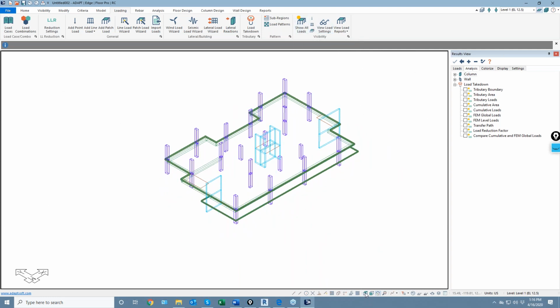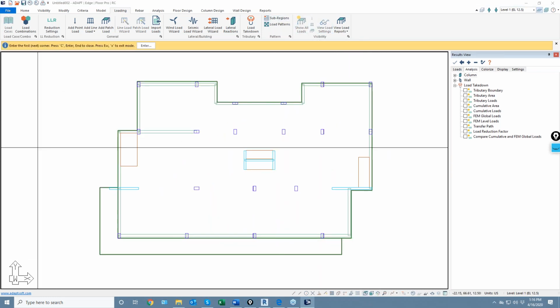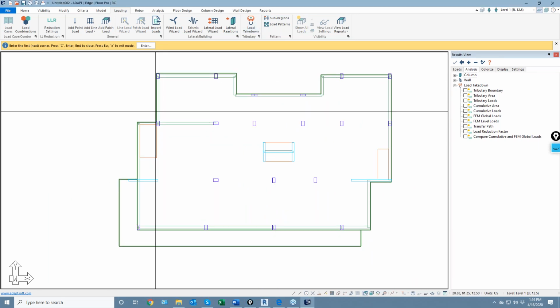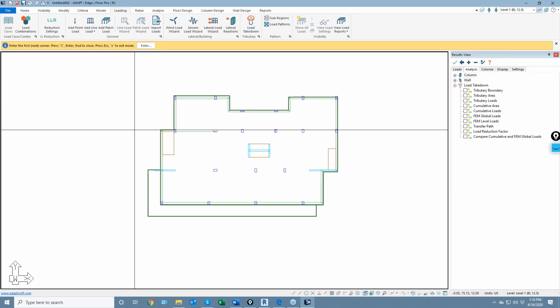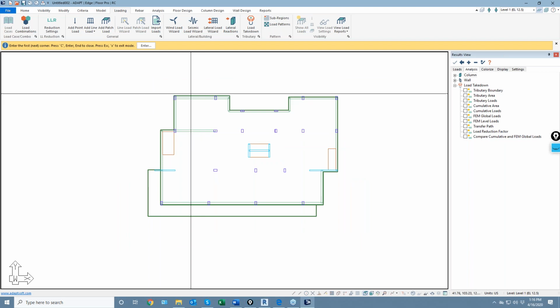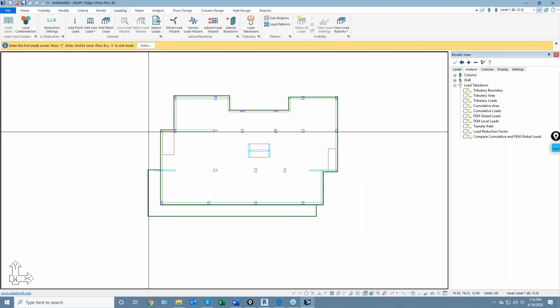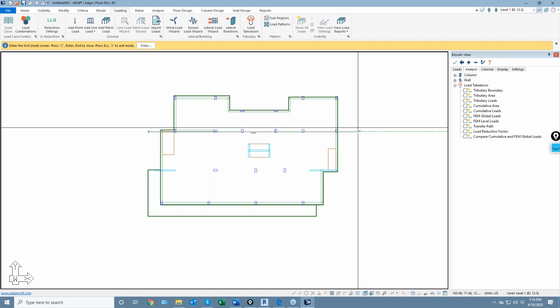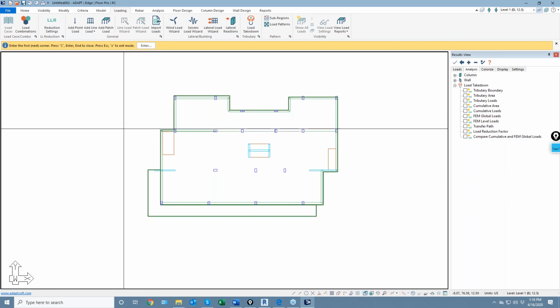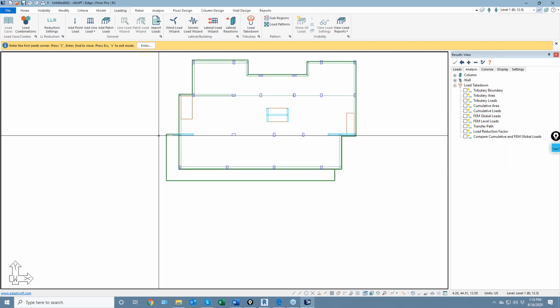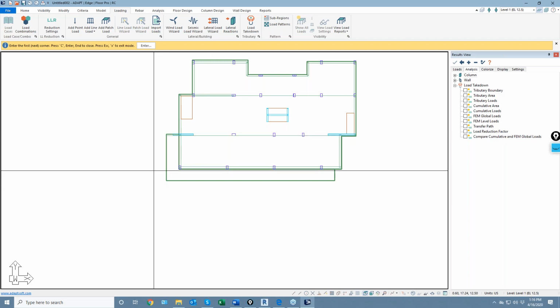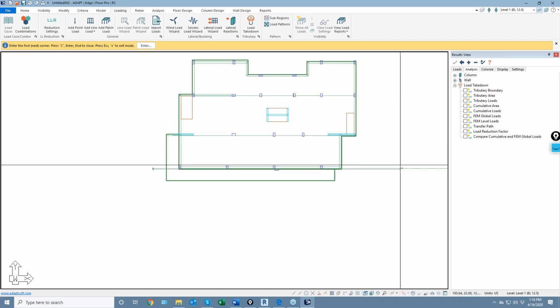So I'll go back here to subregions, and I'm going to create multiple regions in the slab. I could draw polygons. I can draw dividing lines is really what I'm going to do. So I'm going to click a point and I'll click another point. And then in this case, we'll do this region here. And I'll actually do a region there.